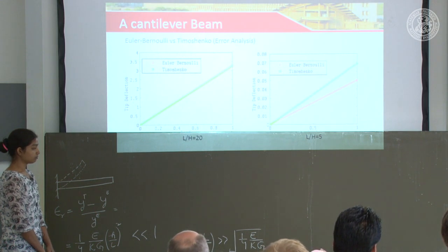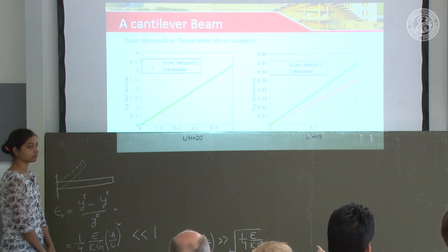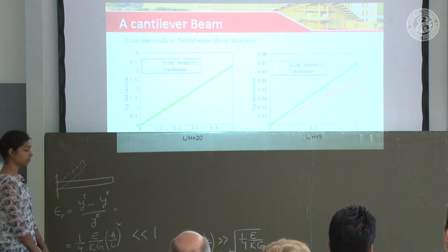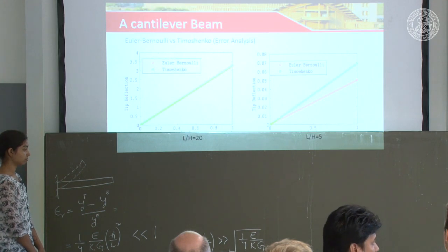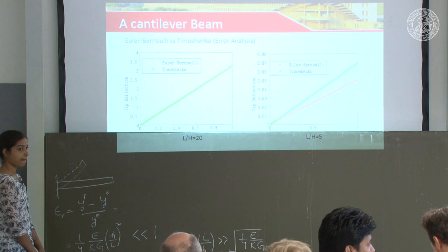So that constant 1/4 will change. And this is due to the shape of the cross section. It's different for different shapes. So actually, the factor of influence is 1/4 kappa, which changes due to the shape of the cross section, or which will change if you change the axis or the plane of the deflection of the beam. Okay. Thank you.